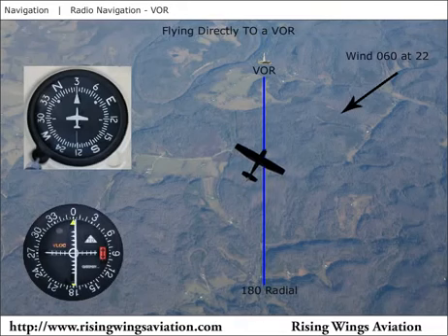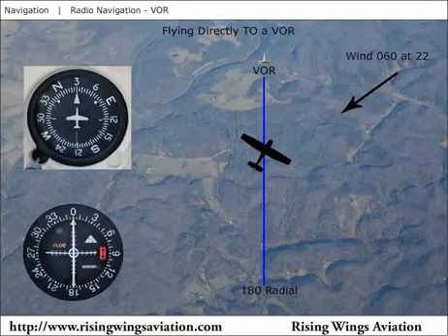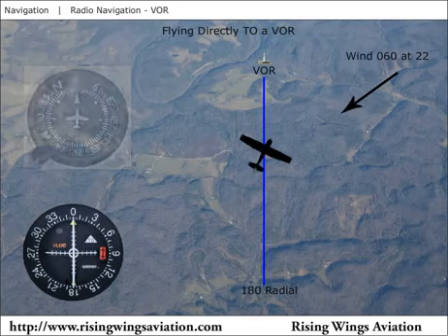Once the needle is centered, we make a guess as to what heading will perfectly counteract the wind. We know from our experience so far that a 030 heading more than counteracts the wind, but a 15 heading fails to counteract the wind. So we should pick a heading between these two. We decide to try a 020 heading.